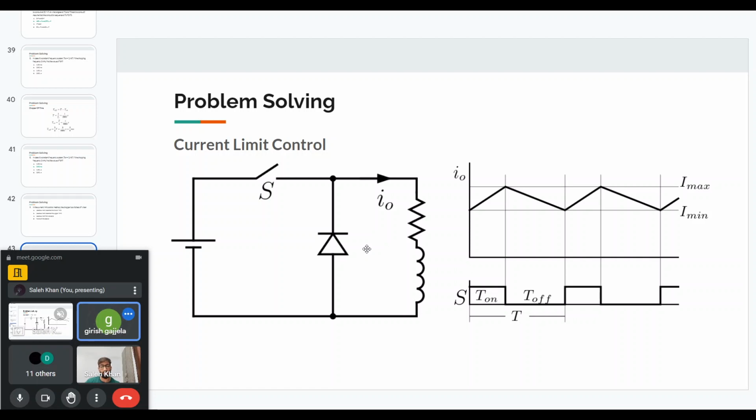Okay, so in this kind of a chopper circuit, you don't really need that inductor because the load itself is inductive. So we will just take the inductance of the load itself. So in RLE DC motor kind of a load, we don't need an inductor and then a capacitor and then the load.